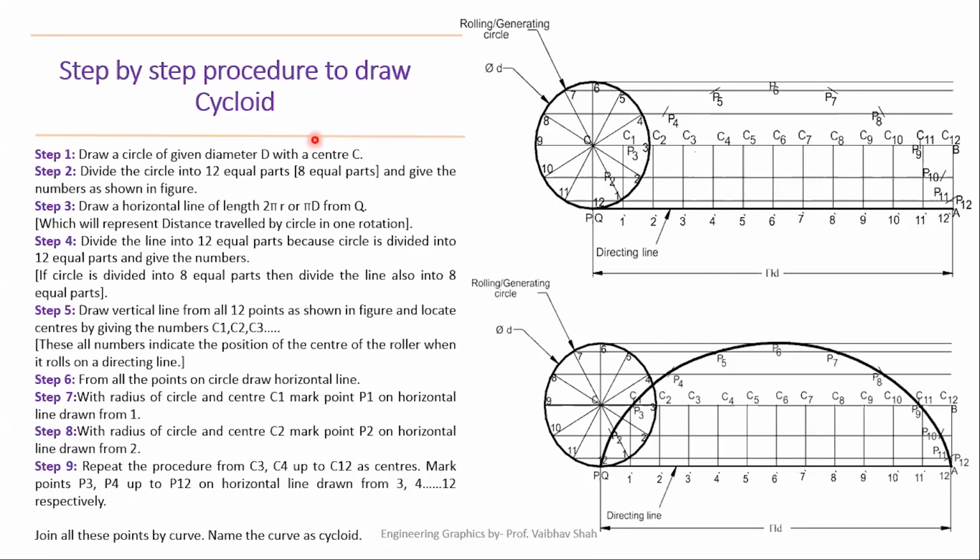So now we'll be given the circle diameter or circle's radius. So we'll always be starting with either the diameter of a circle or a radius of a circle. So here let us assume in our case we are provided with a diameter of a circle. So first let us construct one circle with the given diameter d, and we'll identify its center as center point C, or you can always write it as center point C0, which will denote the initial position of this circle.